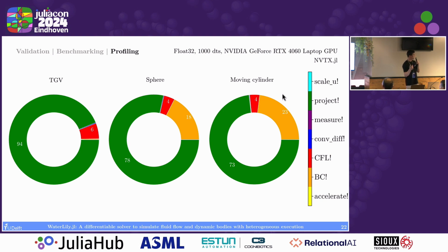On the other hand, when we compute the convective and diffusive terms of the Navier-Stokes equation through the comp_diff kernel, it's almost a pointwise kernel that only looks at the Cartesian indices in the array. This is very, very cheap on the GPU. You can hardly even see this kernel here. So the bottlenecks are basically the reductions on the GPU, I think.